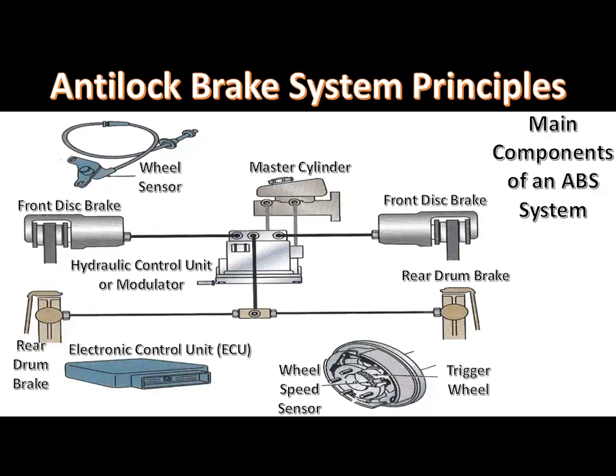In the event of an ABS system failure, the brake system should operate as a conventional braking system without the benefits of ABS. The components that comprise the ABS include the electronic control unit, or ECU, the hydraulic control unit, or HCU, the wheel speed sensors, as well as the brake booster and master cylinder.